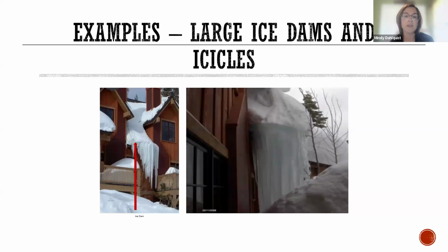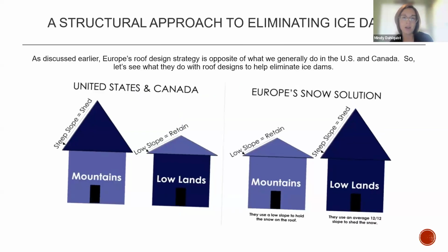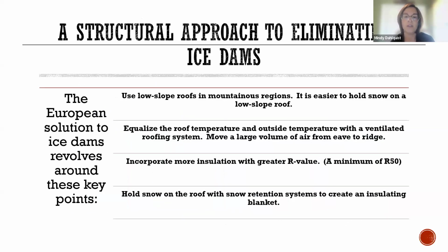Ice damming, I'm going to run through these. I'm sure you know what an ice dam is. That heat loss that I discussed earlier, about how the ridge of the roof loses the majority of the heat, and as you get towards the eave, it refreezes. That actually is what causes the ice damming concerns.